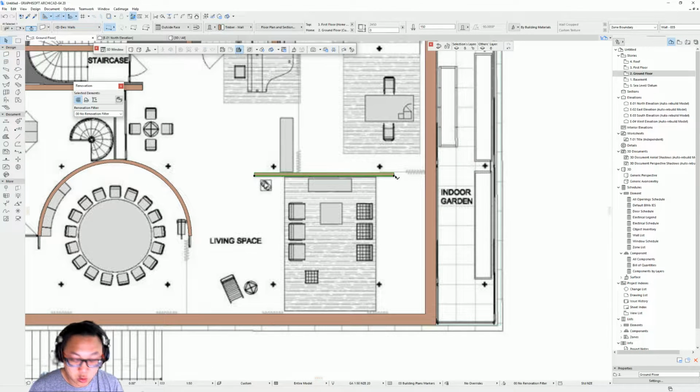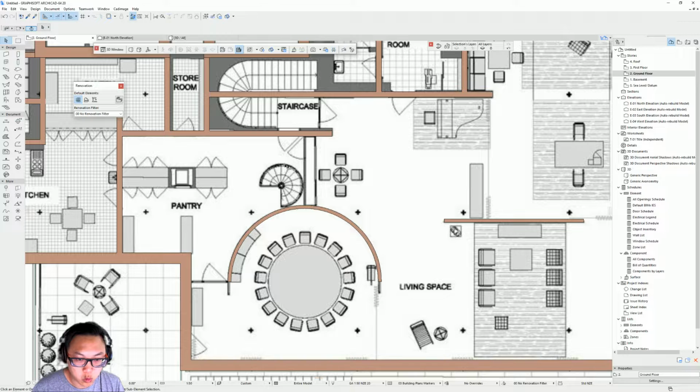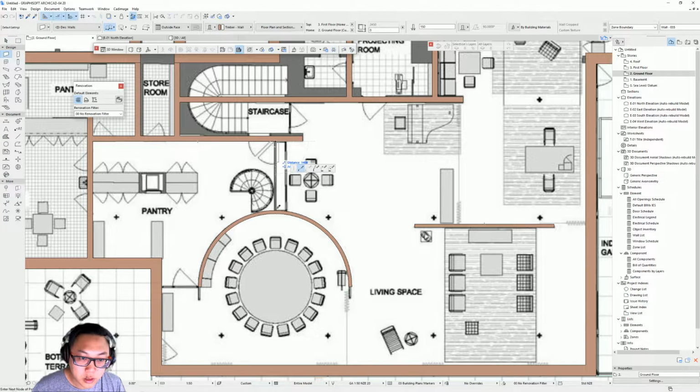And because I don't know exactly what's the distance, usually I'll take it, Control D, so I can move it around, go against that wall. As you can see, 6416. So let's say I want a 6400, so I'm just going to move it 16 millimeters, a tiny bit, but now you can see it moved and it's at the correct position. I think that's not a wall, it's just like a staircase that's round. But here we got 2 more walls, so I'm just gonna create those.